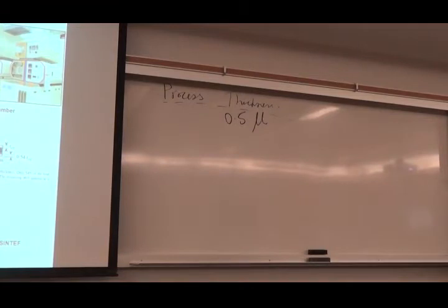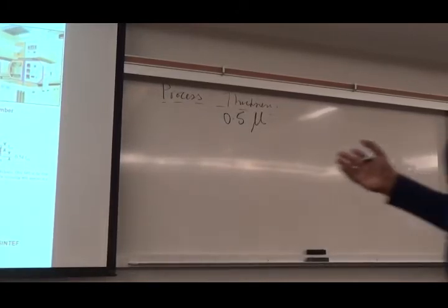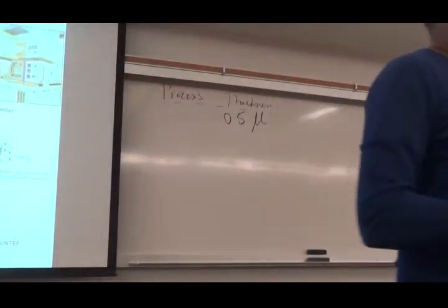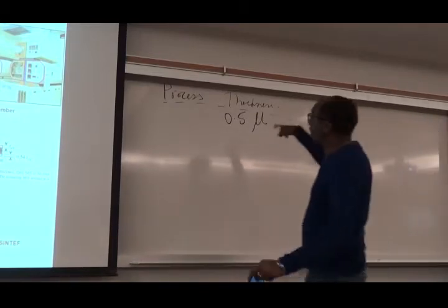So with 0.5 micron, you should get insulation. Remember, the reason I want oxidation is for insulation. Okay? So what is the other insulation layer that we talked about last time? Anybody? Remember, that was what material? So silicon dioxide, insulation material. So one is you grow an oxide, the other one is you grow nitride. Very good, silicon nitride. But anyway, oxidation, typically we go 0.5 micron.